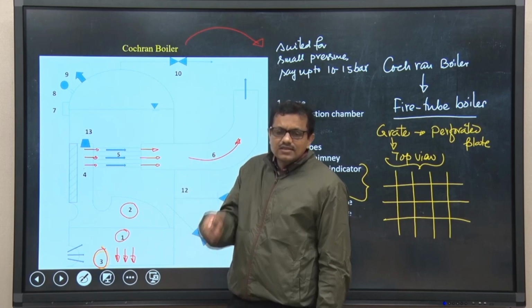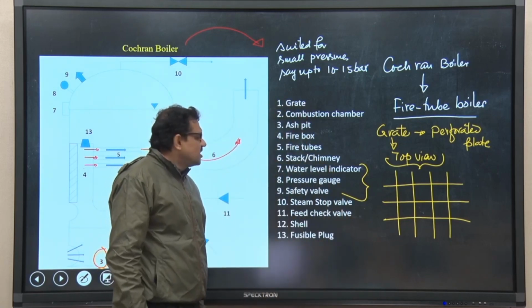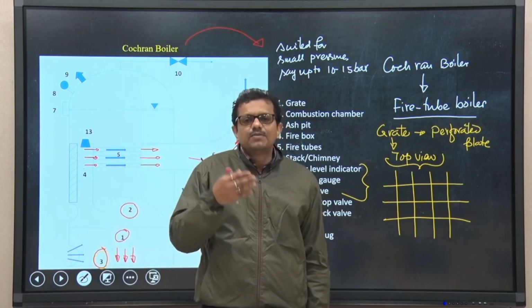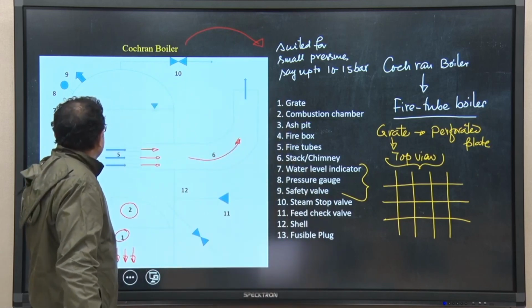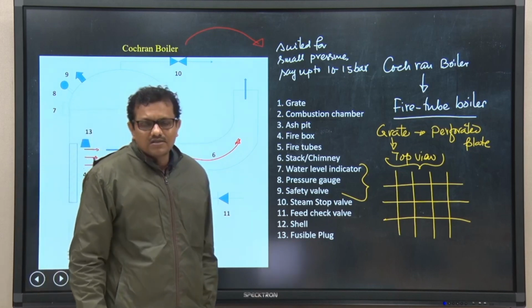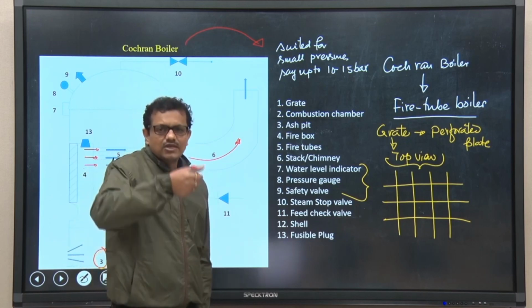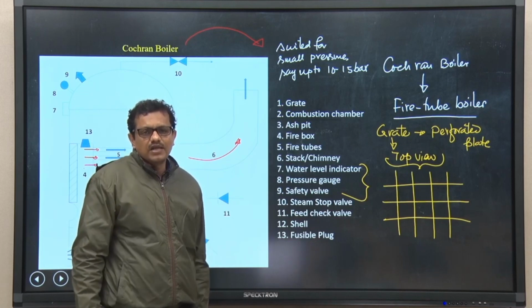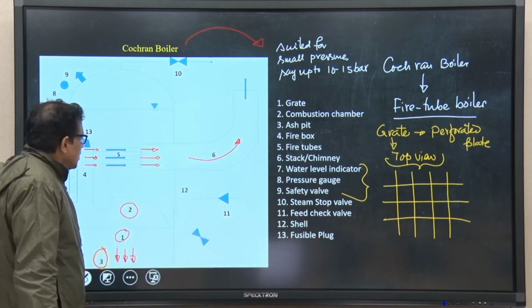These two components, the pressure gauge and the water level indicator, are responsible for checking the pressure inside the boiler. And the safety valve, in any case, is given because if the water level falls, pressure will increase. So, the operator will be in a position to open the valve to remove the steam from the boiler, essentially to save the boiler from the expected accident.